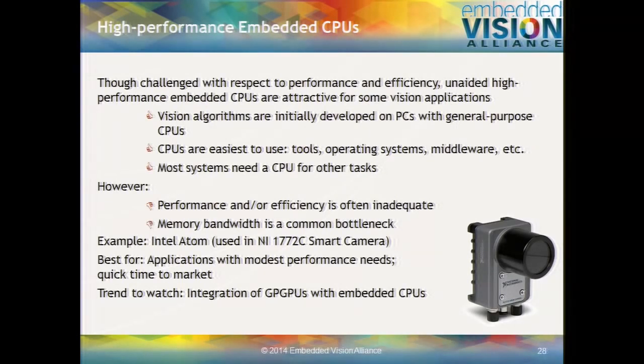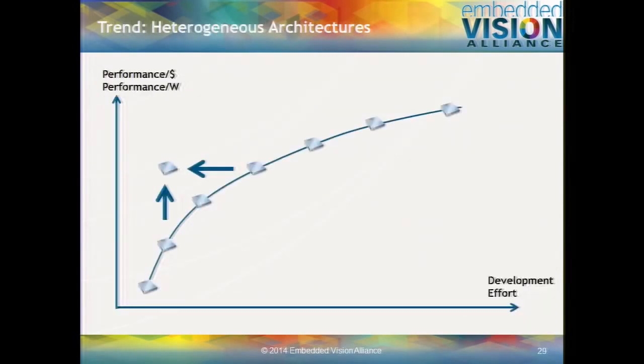And you can see that with a mobile phone. If you take a typical smartphone today that's got 2 to 3 gigahertz ARM Cortex-A15 type cores, and you just max them out, it can't run in that state very long. It starts to get too hot, and thermal limiting comes into effect and forces the CPU clock speed to go down so the phone doesn't melt. So this obviously isn't going to work for a lot of applications. It isn't very energy efficient, it isn't a very cost-effective way to get the necessary performance.